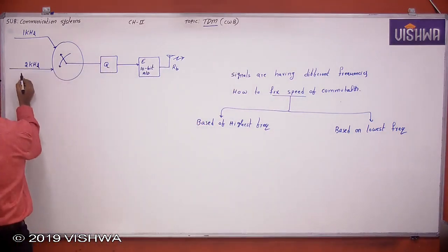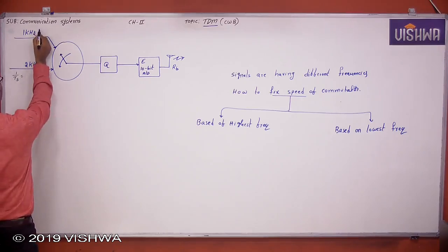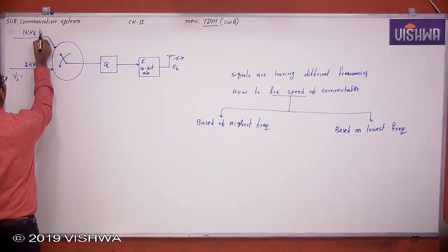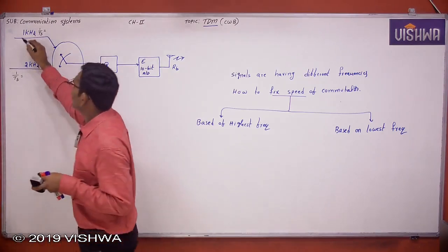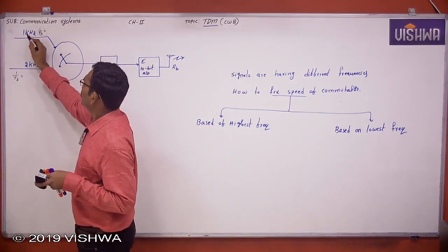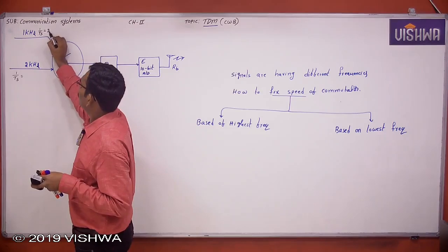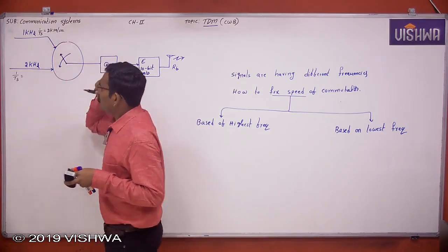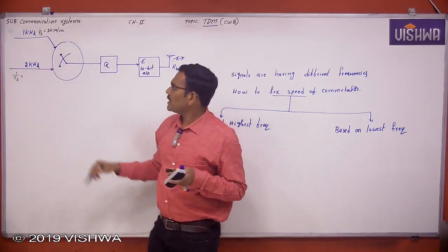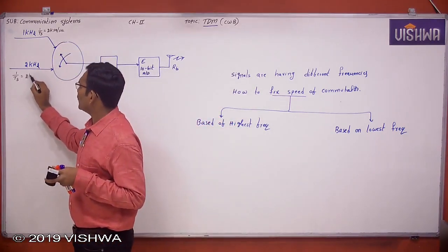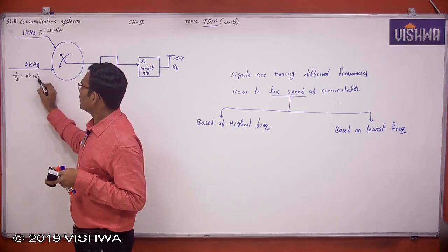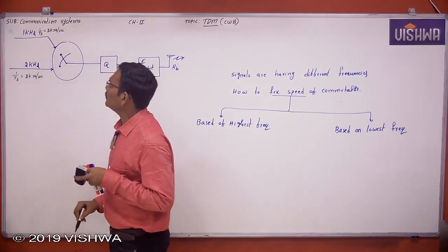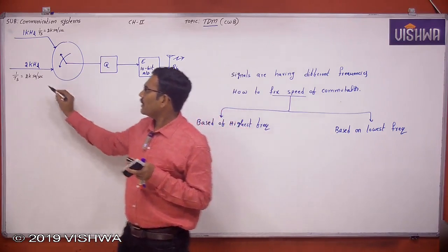The sampling rate here is the Nyquist rate, 2 omega. With omega 1, that is 2 kilo samples per second. Now if the second signal is also sampled at 2 kilo samples per second, what happens?